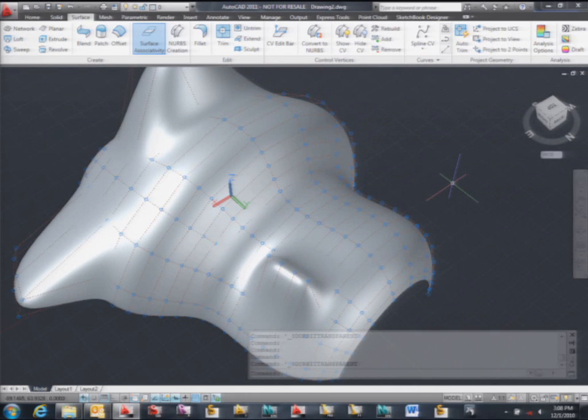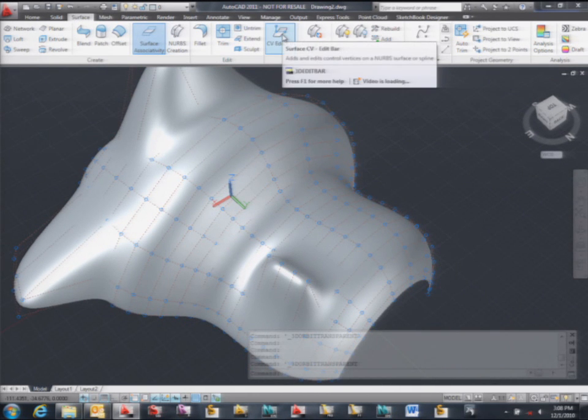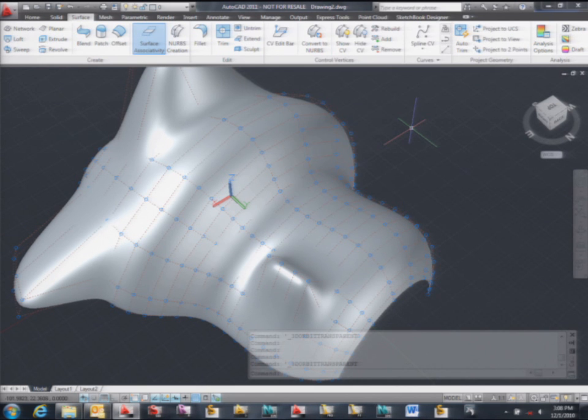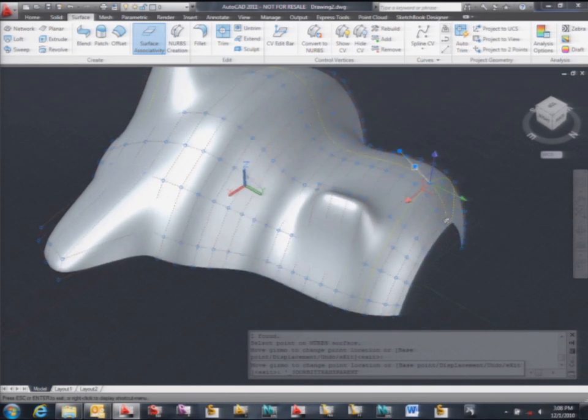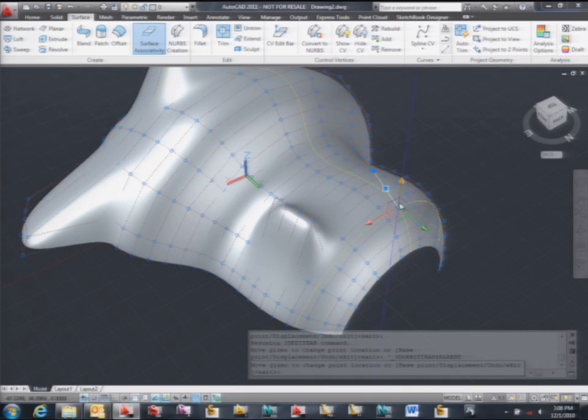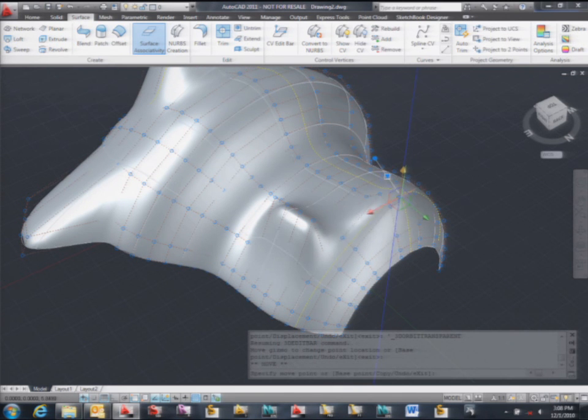The weight. Another thing, when you go into CV edit bar, I was saying that now I added more detail in one direction because I needed more granularity on certain parts, right? But I can go to kind of the ultimate way to do that, which is track any point of the spline of the surface, right? And I really want it here. So once I click on this position, the gizmo appears exactly on that place, and what I can do at that moment is either just directly move the points wherever I want.